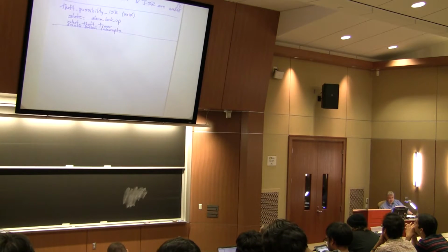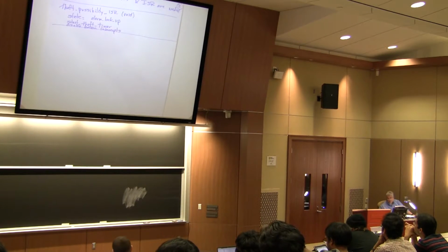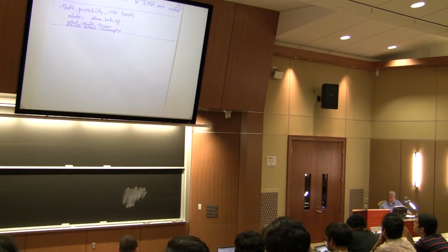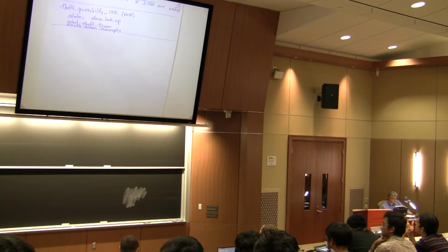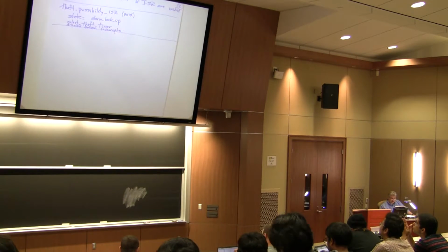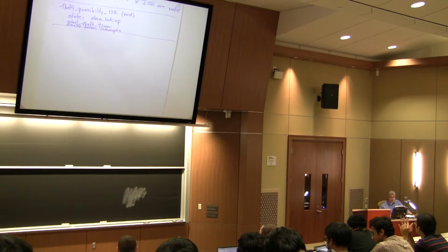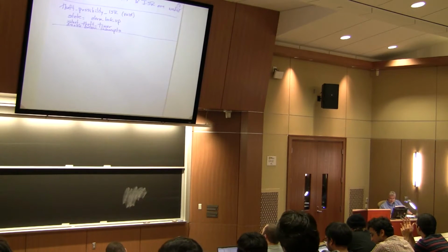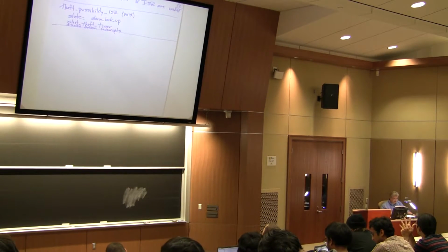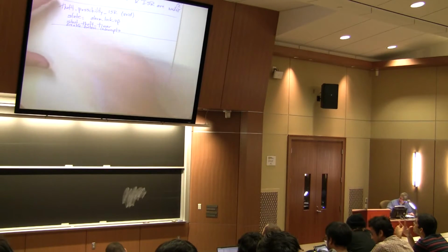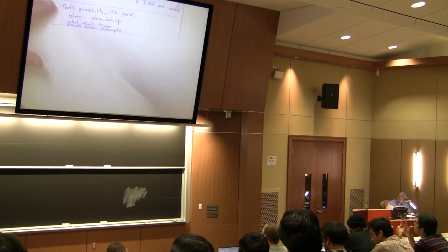Disable button interrupts. It could be a certain level of interrupt. For example, buttons might be low priority and timers might be really high priority. Okay? What about another interrupt service routine? All right? So this would be the return button, right?